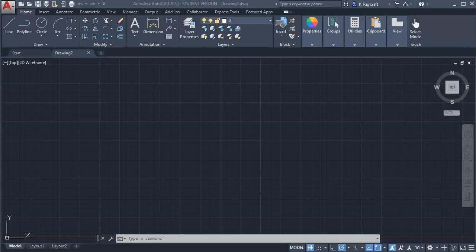Within an office, when new projects are started, typically a template file is used, and a template file would already have certain settings defined, such as title blocks, paper sizes, printers. Another important feature that would be incorporated into style is dimension styles, text styles, and multi-leader styles.